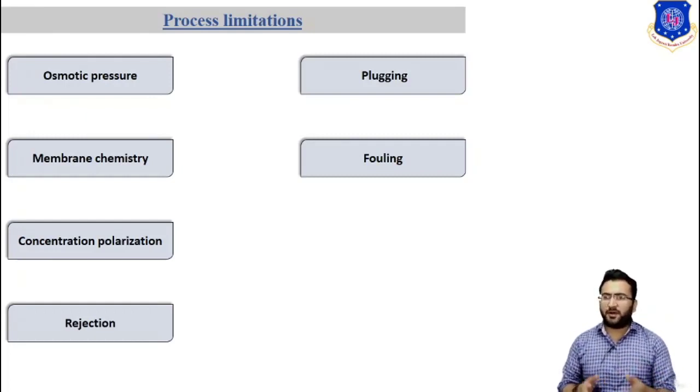Now let us discuss the next parameter, which is plugging. The silt carried into the membrane module may deposit and plug it. Membrane configurations differ in their ability to tolerate suspended solids, with the hollow fiber fed cell side being the least tolerant and large pore tube fed tube side being the most tolerant. Membrane manufacturers use the silt density index to show the tolerance to suspended solids.